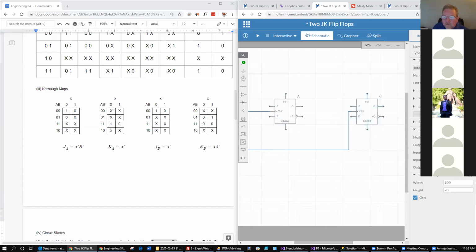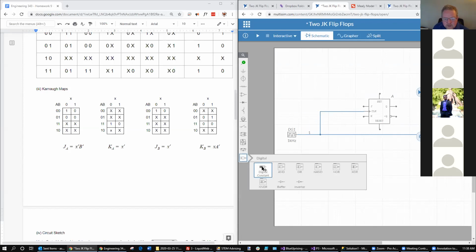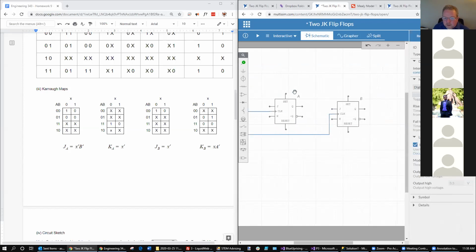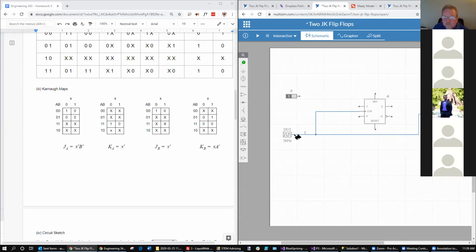And then what we need to do is have some kind of toggle for our input. I think where we found that was down here, a constant that we put right here. And then the value of this is going to be X. And this is what we're going to toggle back and forth as the clock is moving through. It cycles from 0 to 5, 0 to 5 over and over. Here's our input. All right, based on these 4 equations, what kind of logic gate do I need to pull out of our toolbox and put onto the screen? We need an AND.